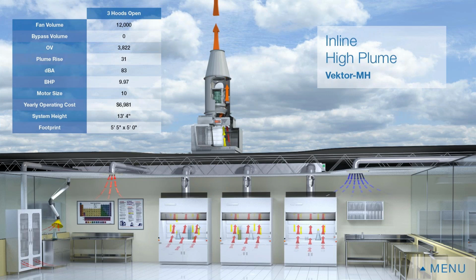Control loop number 2 is going to be how you pressurize your space. So that air coming back down into the space, typically that's going to be a negatively pressurized space. You will run into different situations where it may be positively pressurized. Mainly OR suites, from what we see, would be positively pressurized, but usually that's going to be a negatively pressurized space. So that's control loop number 2. Control loop number 3 is going to be your duct static.